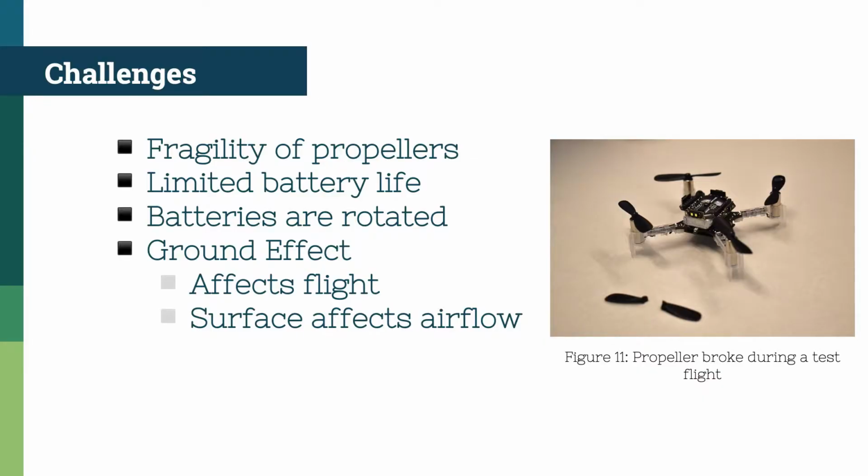The third issue is, again, ground effect. Ground effect is something where the airflow over the propellers ends up deflecting off the ground, and this makes the drone rise up very quickly. But because it rises up at a rapid pace, it can't maintain its stability, and it moves away from where it started. And this was not an issue during the beginning process because our algorithm was only running parts of what it was supposed to do. But during flight tests, it started moving away from where it started, and this meant that it was a major source of error during the later part of the project.